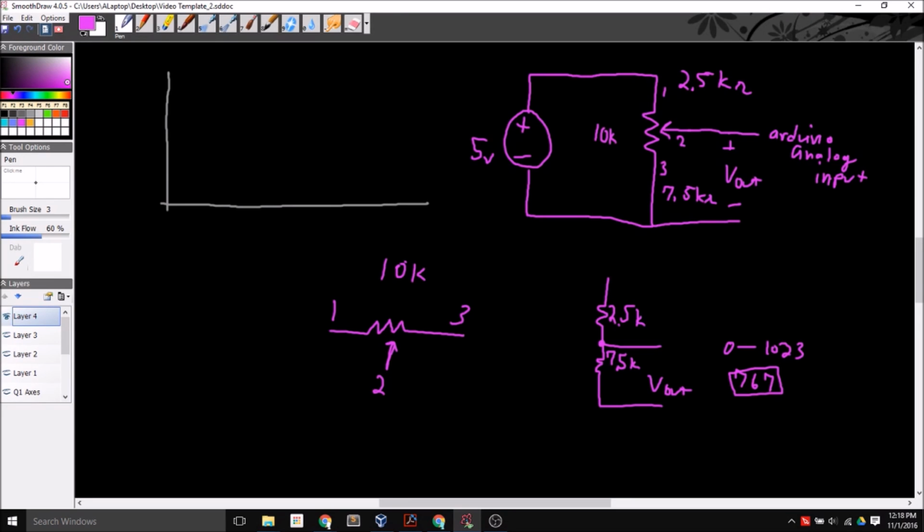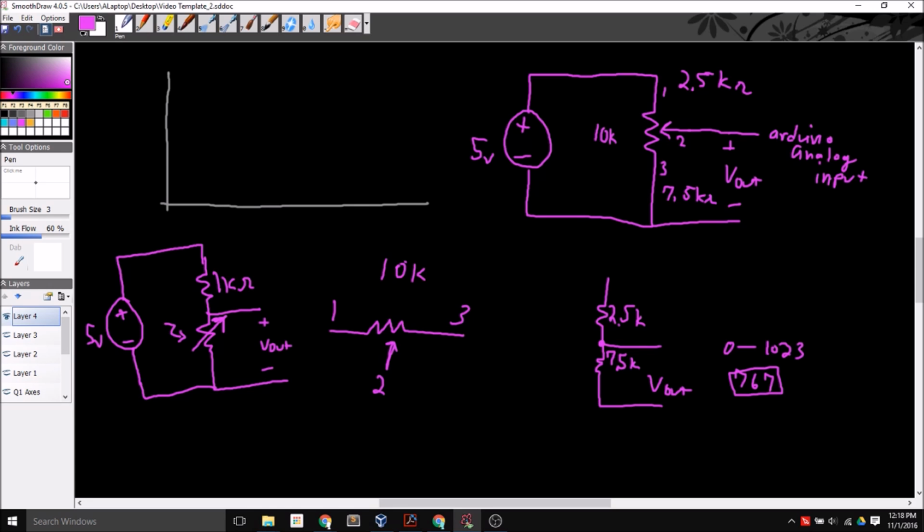Basically just put your soft potentiometer in series with a 1K resistor and connect that in place of your potentiometer on your Arduino to look like this. And usually when you have a sensor, you'll have a symbol to reference that there's a sensor here, and this has a light input. And then you should be able to get similar kinds of functions on your LED based on how much light is coming into that photocell.